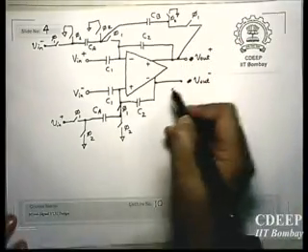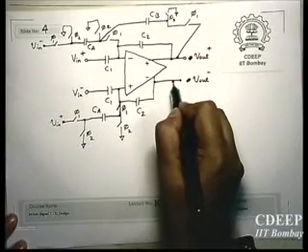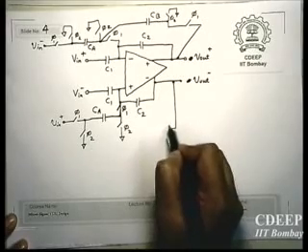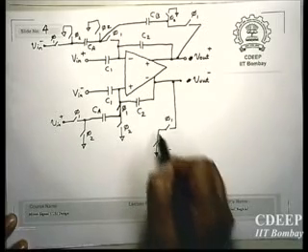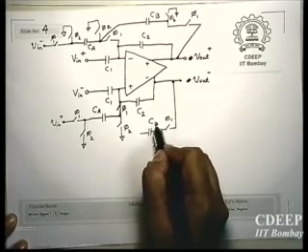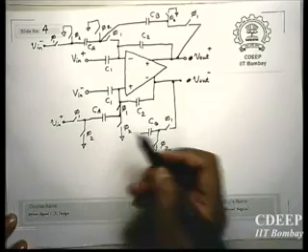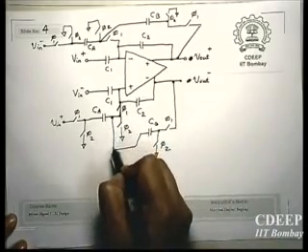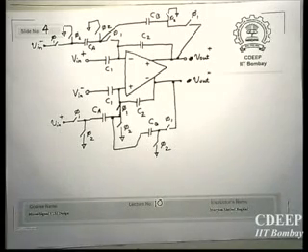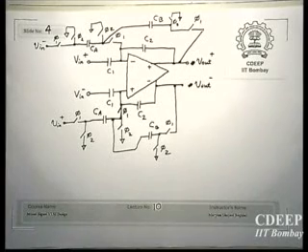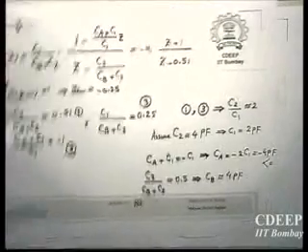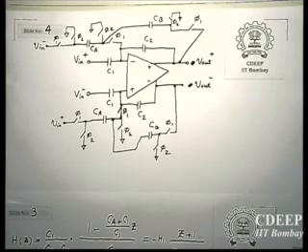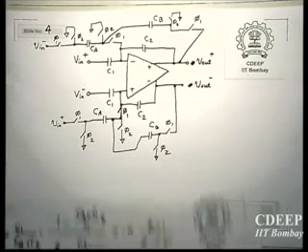And similarly we will have here again phi 1, phi 2, then capacitor CB, and CB doesn't need the left side, they are already there, so we just connect it to the right plate of CA. So now this is a fully differential architecture of the same filter that we designed here. And then the values will be, for example, these. You could have used a smaller capacitor. Now, there is one small point regarding the value of the capacitor.